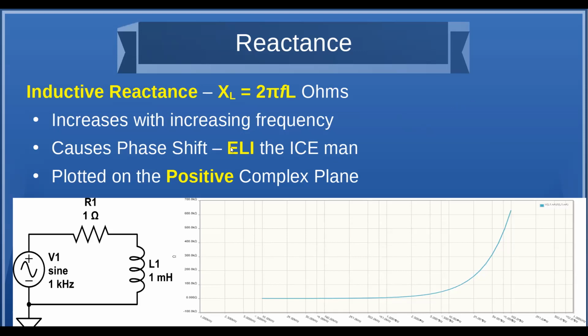It means initially on the inductor, we apply a voltage to it. It's going to essentially apply an equivalent resisting voltage, and the current will be 0. Over time, the current will increase and the voltage will drop, just the inverse of the capacitor.